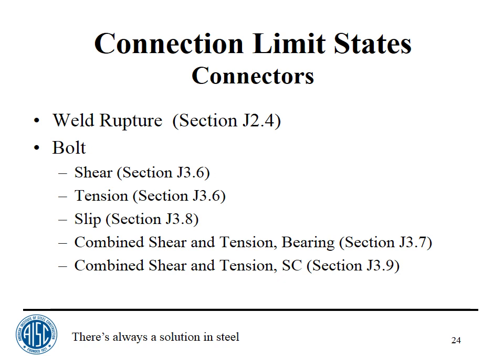I would say that the advantage of the tabs is primarily in erection, because it's extremely easy to erect a beam with a gusset plate if you can bring it in laterally and pin it. Whereas if you have double clips, you've got to basically jam it between the column flanges if you're talking about a flange connection, or you've got to drop the thing down the column web to get it in place. And if there's a stiffener or something in there for a moment connection in the other direction or at a different level, that might be a problem. The tabs make the erection very simple.